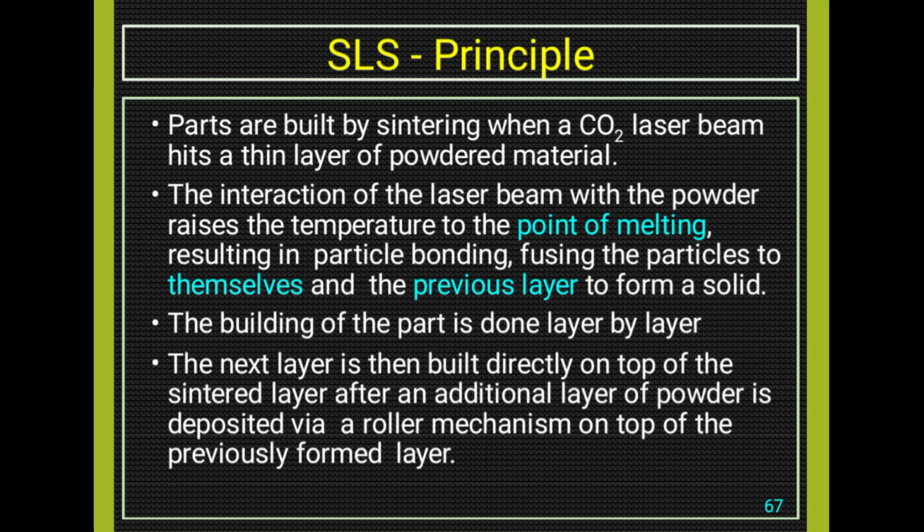The building of the part is done layer by layer. The next layer is then built directly on top of the sintered layer, after an additional layer of powder is deposited through a roller mechanism on the top of previously formed layer.